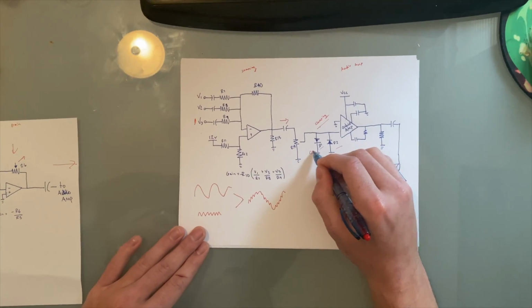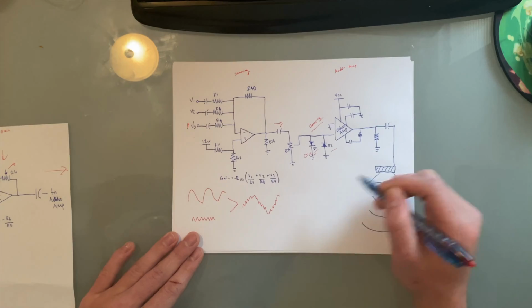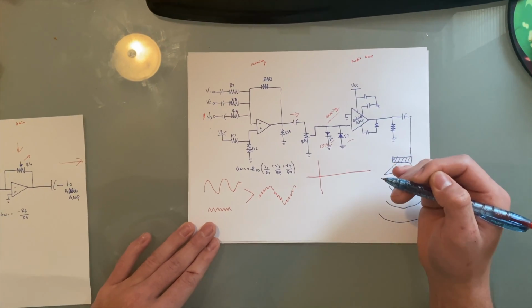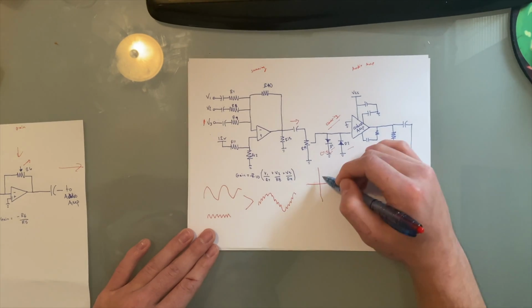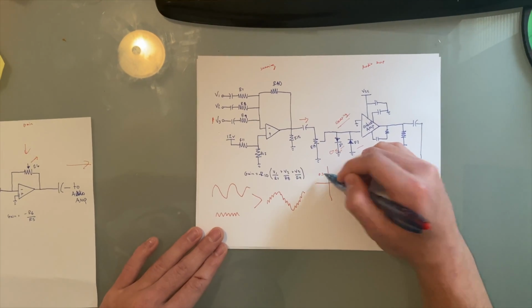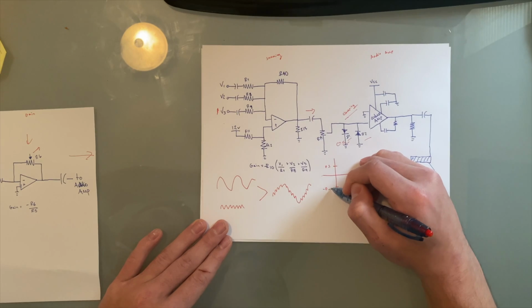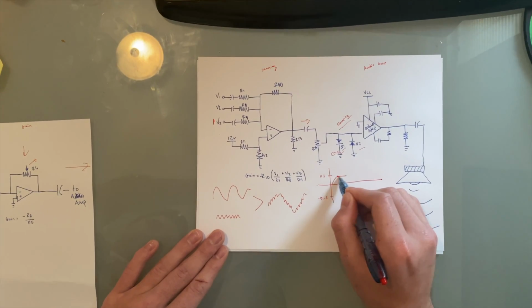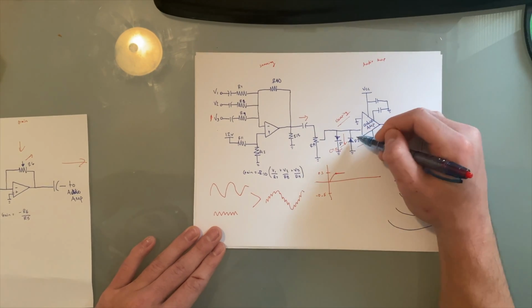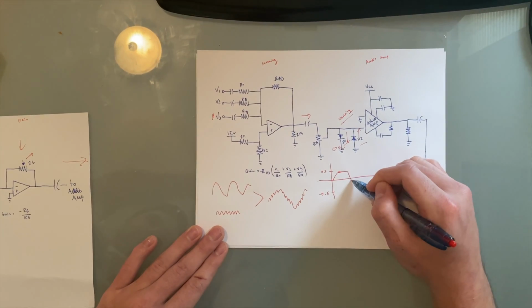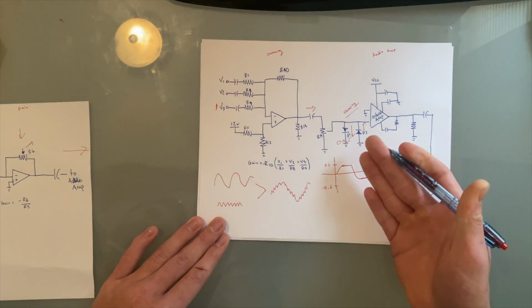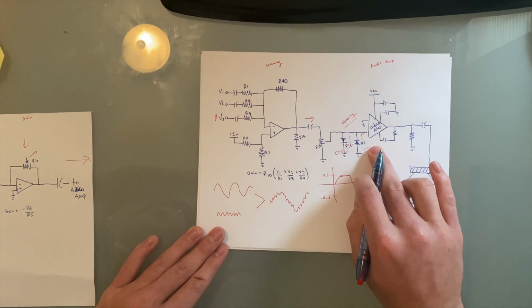So these require a 0.5 volt forward voltage to operate. So if your signal is greater than 0.5 volts, it will clamp it. So here's 0.5. Negative 0.5. So the signal will stop right here and clamp if it tries to go over, because it will short it to ground either way. So it clamps it right there, but a smaller signal is fine. We do this to protect the audio amplifier, which it's feeding into next.